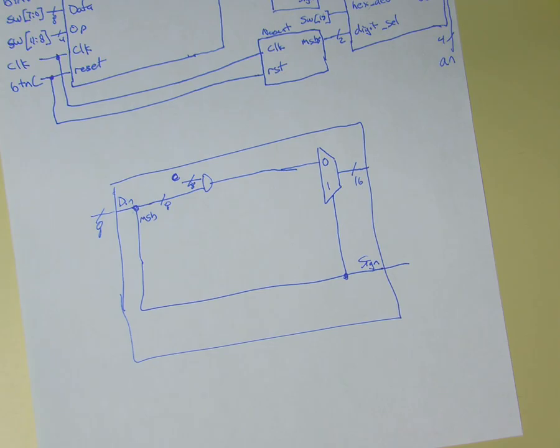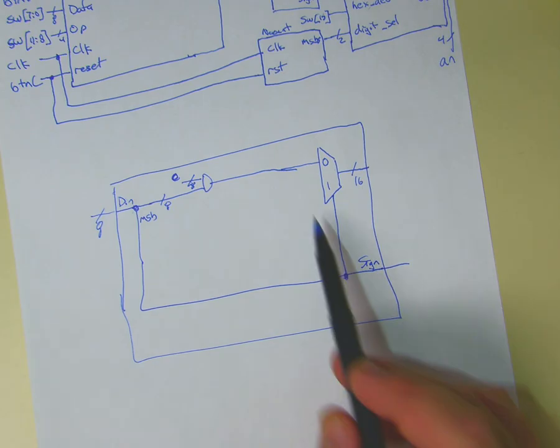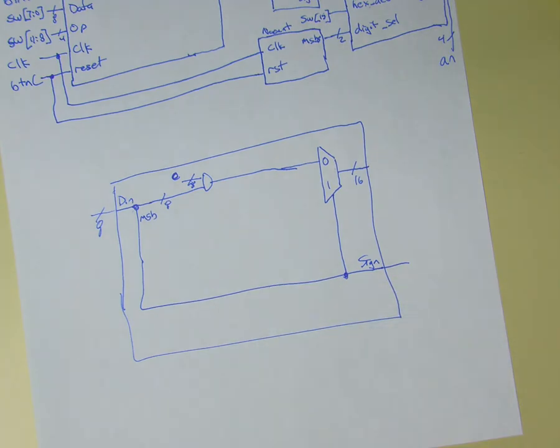Okay. What if, how do I do a 2's complement? Because that's the only thing that's left. I've got to figure out how to do a 2's complement down here. Invert all the values and add 1. Flip all the values and add 1 is a perfectly fine way to do it, right? How do I flip all the values? Let's just do a bunch of NOT gates. In this case, it's not a conditional guess. We just know what it is.